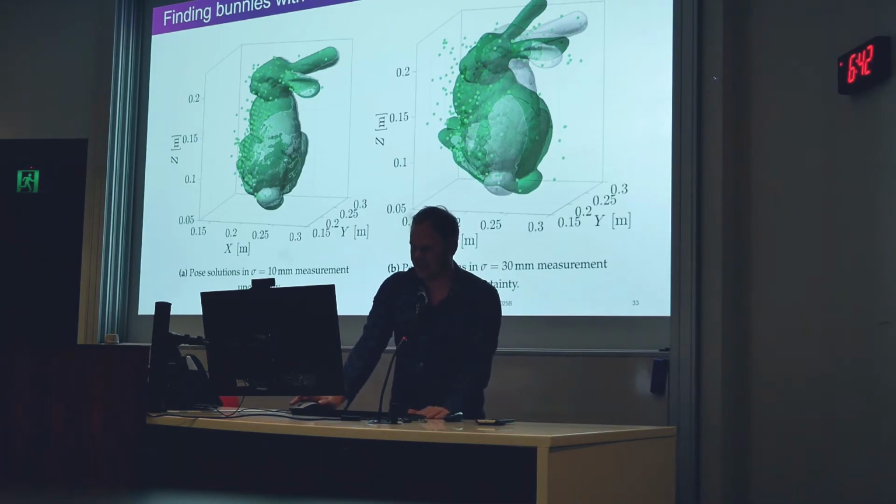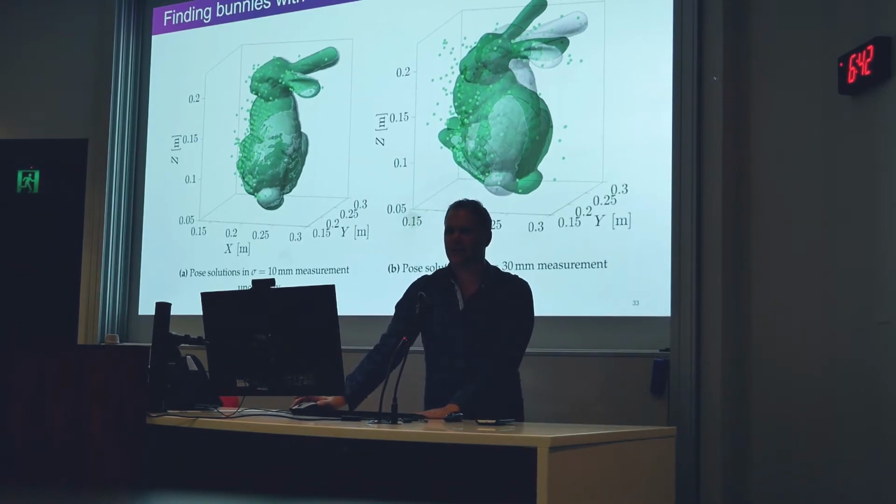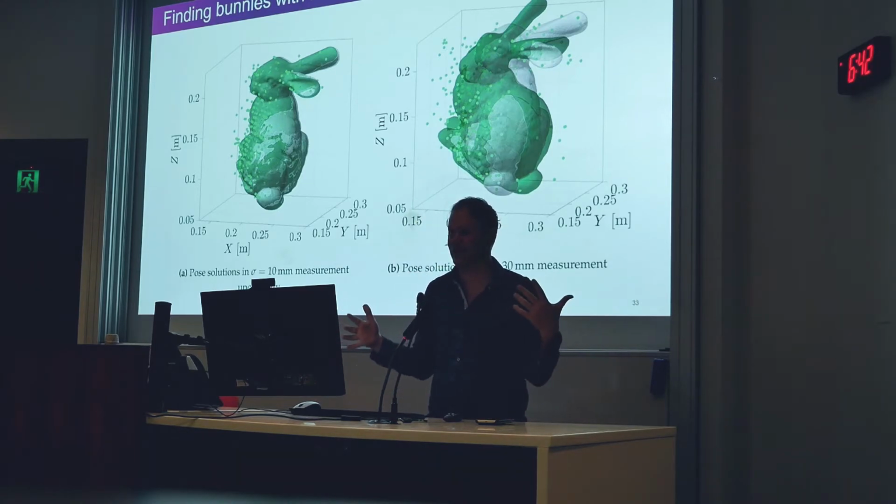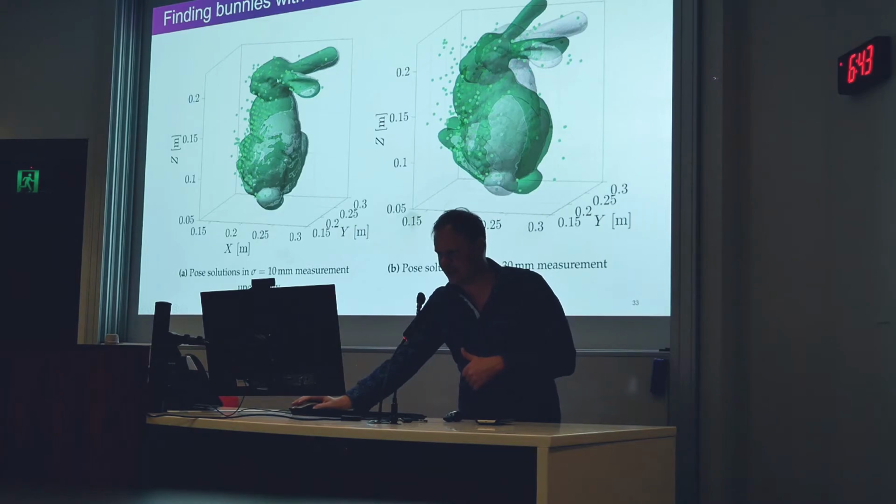All right. What about when the data from the sensor has really large uncertainty in it? What if I bought a really crappy $100 LiDAR and its measurements were like, yeah, we think it's this plus or minus 100 millimeters, right? So as long as the bias is zero, the uncertainty can be whatever it needs to be because we're modeling it. We're modeling the uncertainty in our measurement likelihood function.